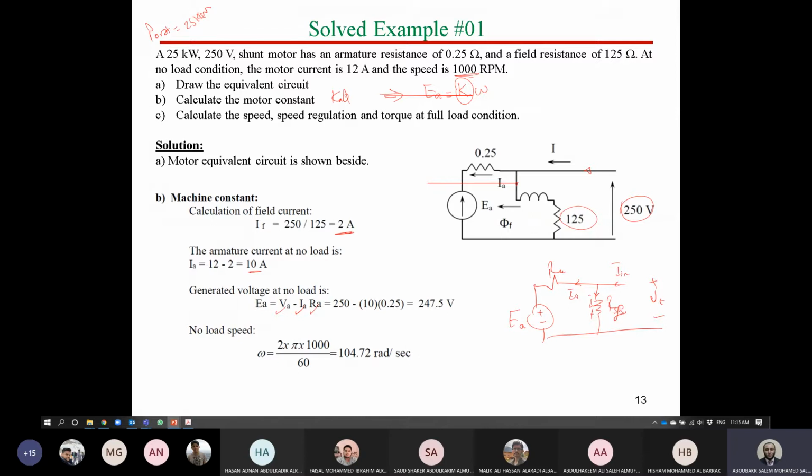By the way, Shabab, I got some questions from your colleagues regarding 2 pi over 60 multiplied by speed. Sometimes there was a problem related to an induction motor, and the frequency was reduced from 60 to 50. And one of your colleagues said to me, we should now multiply by 2 pi over 50, not 60.